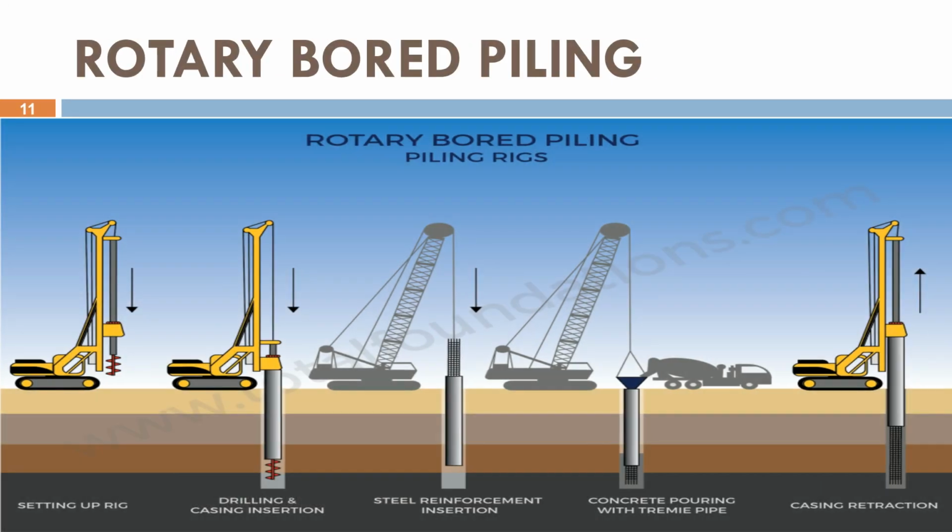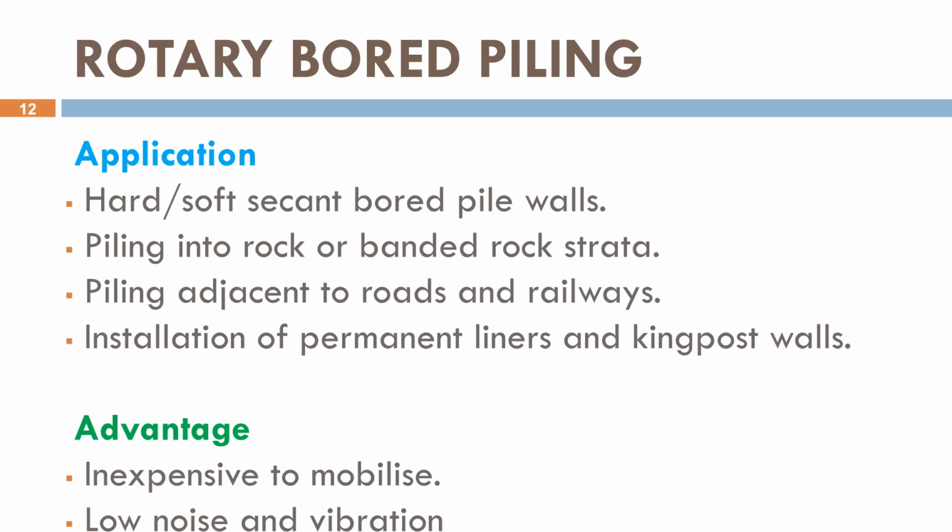This diagram illustrates the process of rotary bored piling, showing the steps from setting up the rig and drilling, to inserting the reinforcement, pouring the concrete, and retracting the casing. We will look into the applications and advantages of rotary bored piling.